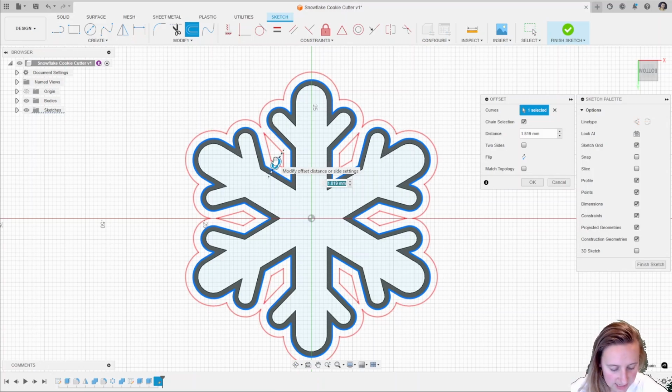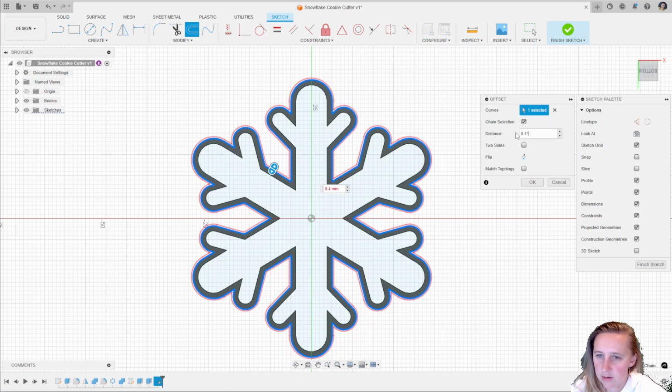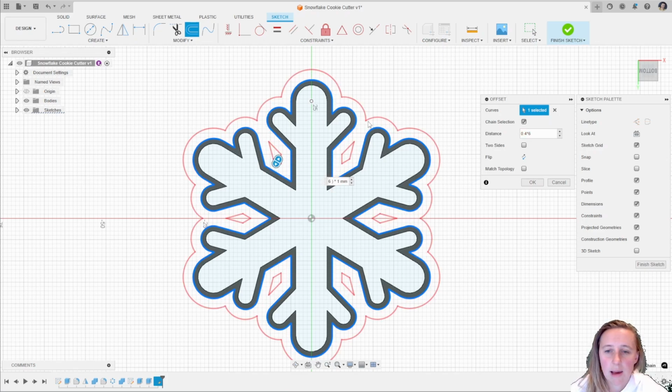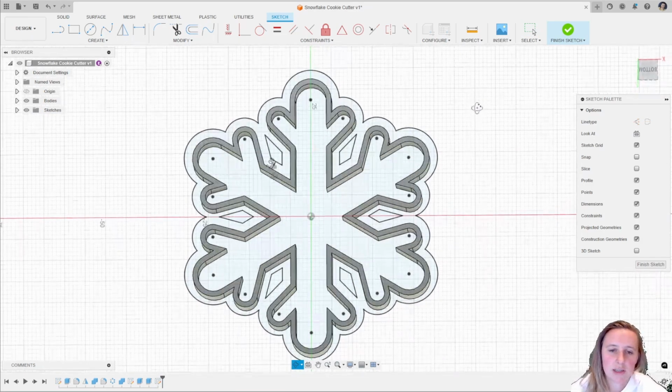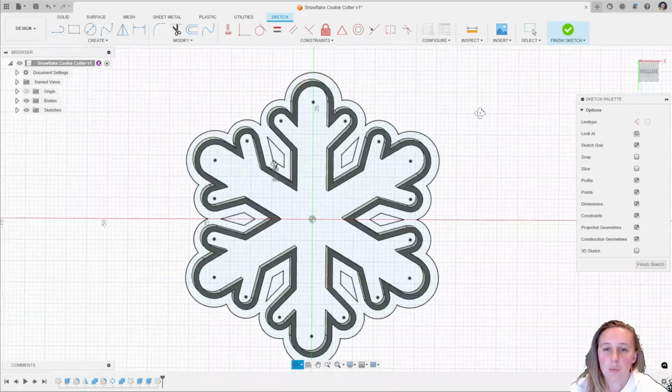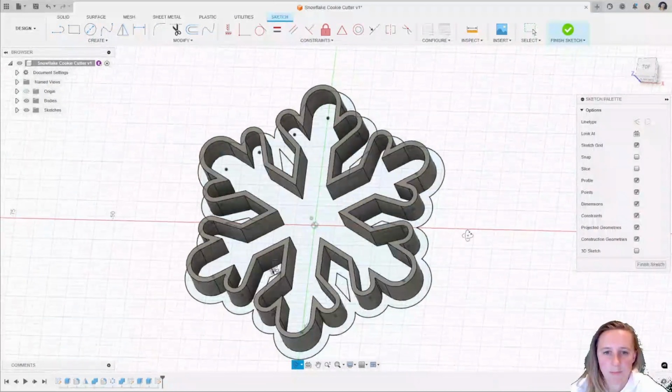And then select a sensible number that I would like. So again, I'd like to use a combination of my extrusion width. So I think that's going to be 0.4 times 6. Yeah, that looks good. 0.4 times 5 might also have worked. Yeah, 0.4 times 5. So that gives me a nice clear number of extrusion widths on my print. So I'm always thinking about designing for 3D printing on these.